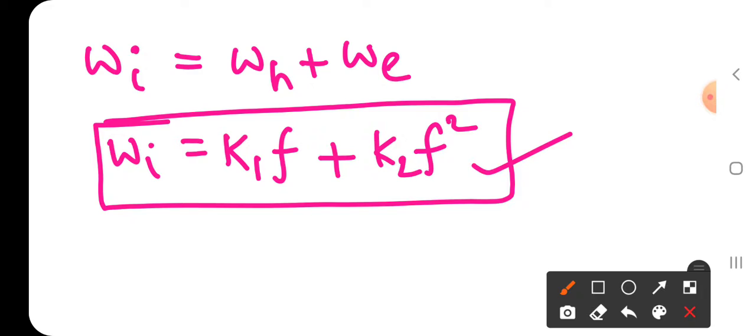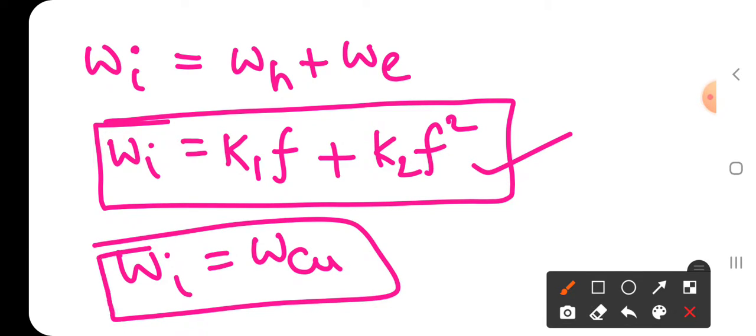That is, eddy current loss and hysteresis loss belong to the iron loss, and the next one is copper loss, that is electrical losses or winding losses or rheostatic losses or resistive losses or variable losses. And we know the efficiency is maximum when Wi is equal to Wcu. That means the constant loss is equal to the variable loss. Whenever the constant loss is equal to the variable loss, then the efficiency of the transformer is maximum.